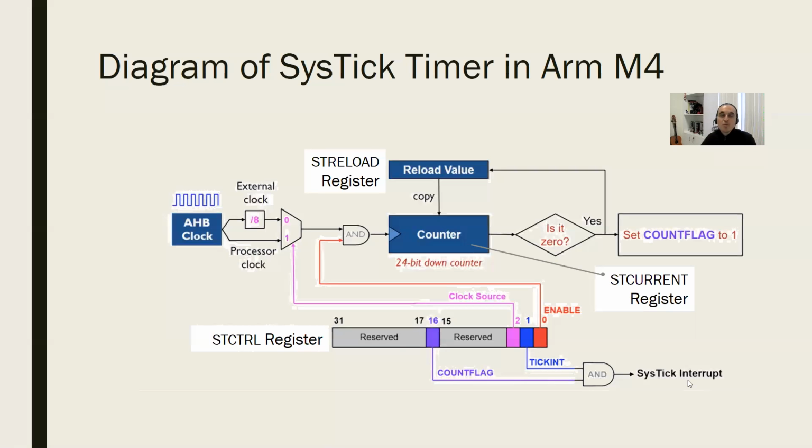Otherwise, no interrupts will be able to come. Do you remember what was the analogy we used for arming that device? The shop being open or the shop door being locked. So if you make this 0, this AND gate will never give out any value other than 0. The shop is locked. This is how you arm it. This is the arm bit.